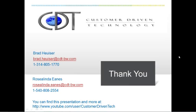And also, Brad, John asked, how can you make an existing sim rep the default rep? So if you want to make an existing rep the default rep, you would just save it as the default rep. You can't save over the master rep, but you can save over the default rep. That's one thing that I get a lot in my training classes. They ask, why is there a default and a master? Why do you have two that are the exact same thing? Well, that's because the default rep you can change, the master one you can't.